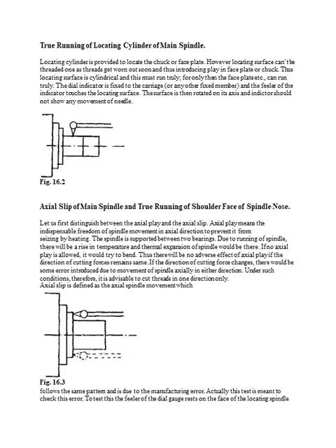See the second figure, you can see that. First it is the dark thick lines. The thick lines show that the dial indicator is touching this part, and after that the spindle is rotated 180 degrees and the opposite side is also checked, given by the dotted lines. Due to this there should not be any variation. The total error indicated by the gauge we can calculate, but it should be within certain levels, otherwise it will be rejected.